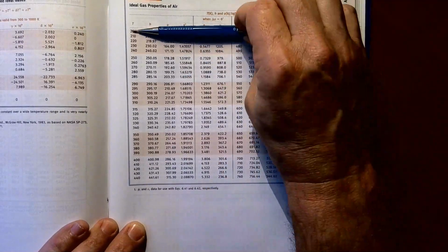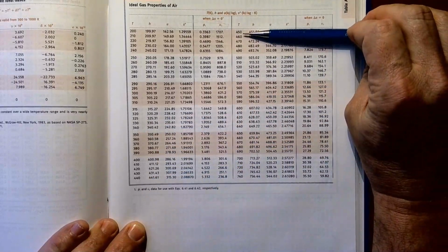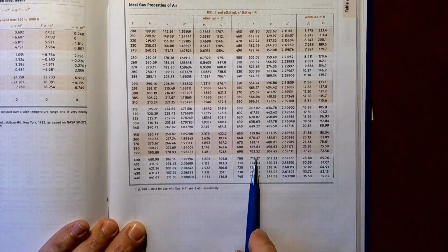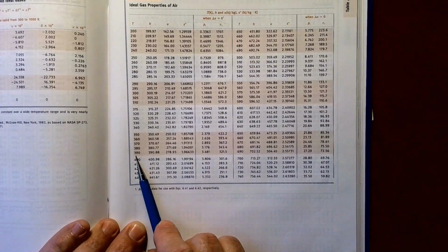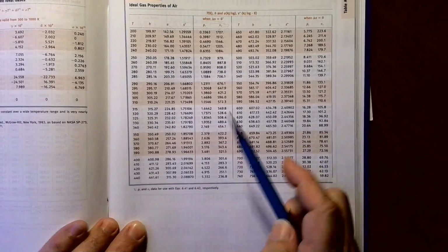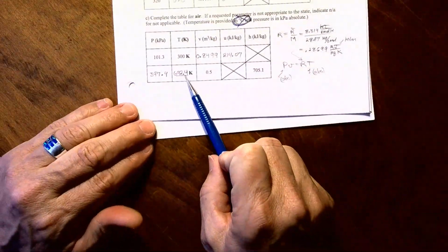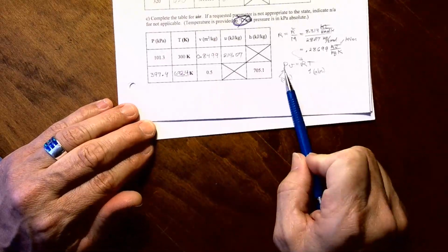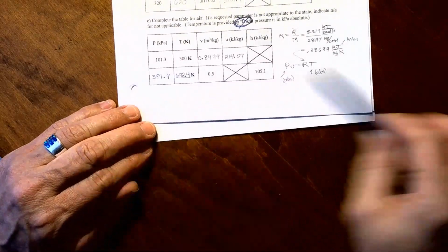So the temperature goes down over here, down to 440. It starts again at 450 on this side and continues down. Some of you actually did the interpolation and went all the way over here to 390 something, 392 I think it ends up being, when it should be 692. So after the interpolation, you get 692.4. You can then take specific volume and temperature, substitute in the ideal gas equation to come up with your pressure, which is 397.4 kilopascals.